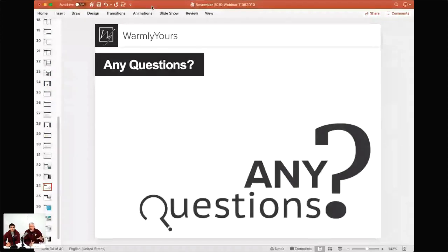It's based on a duty cycle. And here we go, this is going to be 1 minute, not 25 or 30. You'll see multiple, maybe 5 wavy lines on the thermostat. Then sometimes you'll see maybe 3 on the thermostat. That's showing you the duty cycle. So if it's calling for heat and it needs all the heat it can get, all the lines will be lit up.